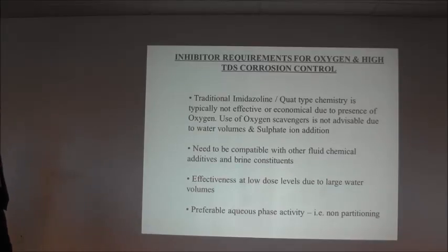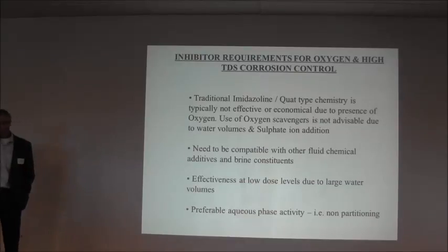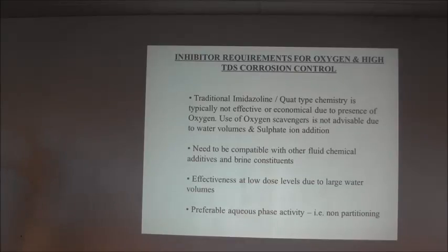So other requirements for the corrosion inhibitors, as mentioned with the scale products earlier on, obviously they need to be compatible with the other fluid additives and compatible in the brine itself. Usually a big challenge with the imidazoline clot-type chemistries is that they are all cationic.